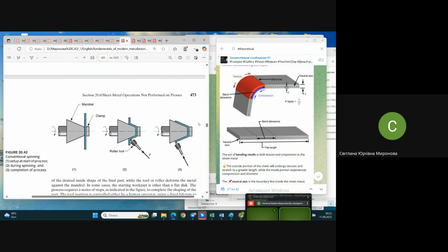If necessary, it may be even more complicated shape, and the whole mandrel punch is made separable. It is assembled from some pieces, and in order to remove it next from the half closed shape, now do imagine that here we have more complicated shape. We just separate these pieces and remove it one by one, and due to this you have more complicated parts.